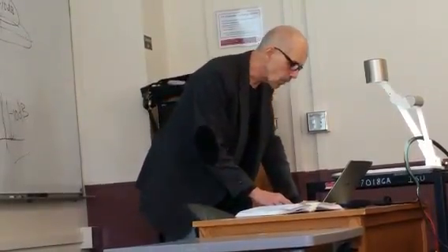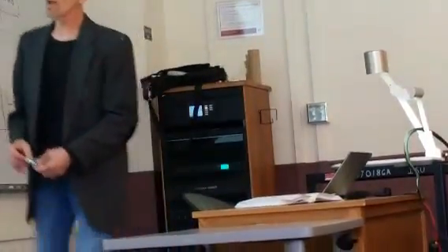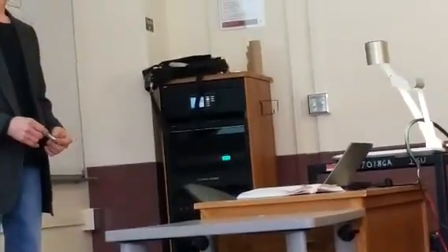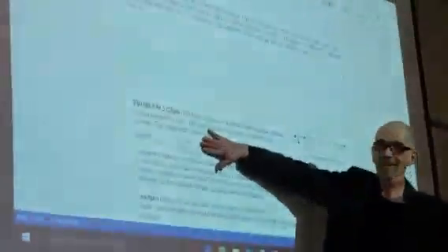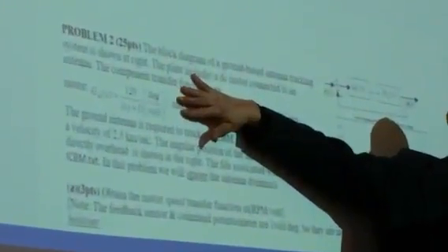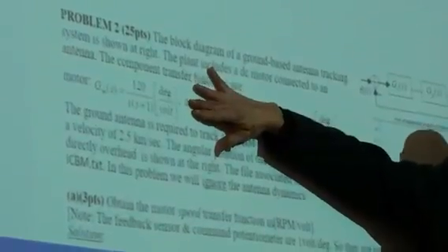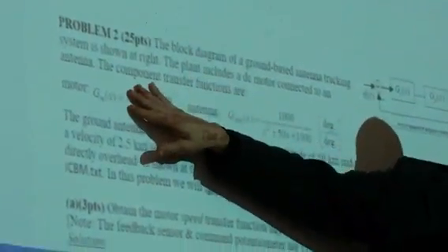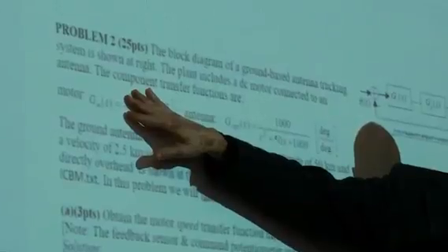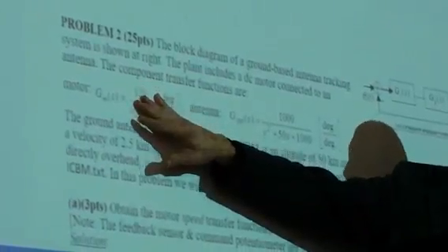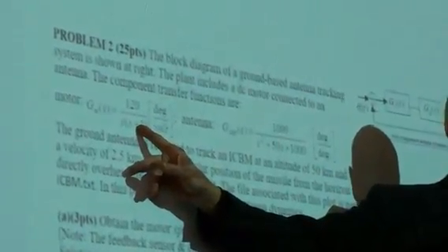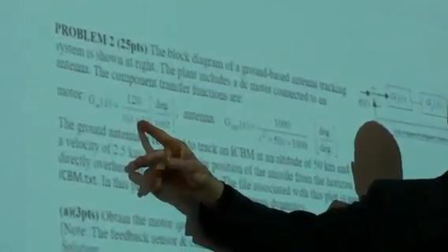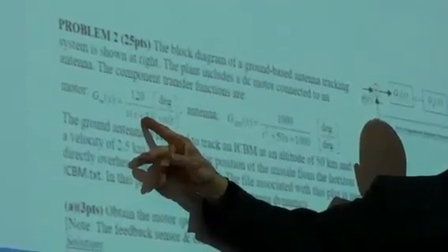All right, let's look at the poles here. Look at this thing. Remember, it's 120. What's the open loop right now? The open loop right now, because this doesn't exist, never has, is this. Okay? Got it? Now you want a controller that cancels that. So the controller has to have an S plus 1 in the numerator.